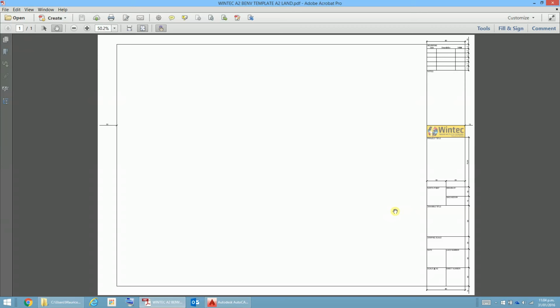Now the main dimensions, just to get us started, you'll see that we're coming 30, and these are all in millimeters. When we work in paper space in AutoCAD, it's always in millimeters, pretty much. So I'm going to come in here. That's 30 millimeters. That's to allow a little bit for binding or stapling. Then you'll see that we've got 15 millimeters around the top here, 15 millimeters down this side, and 15 there. So that's going to give us pretty much the exterior.